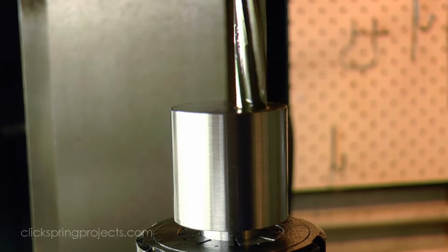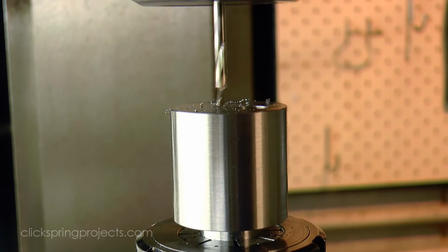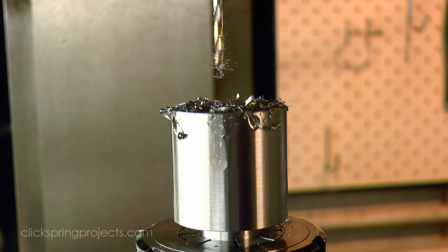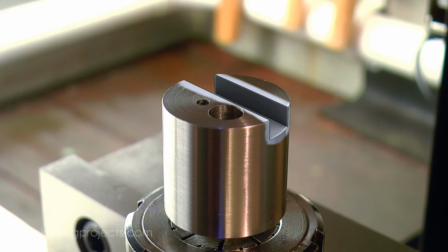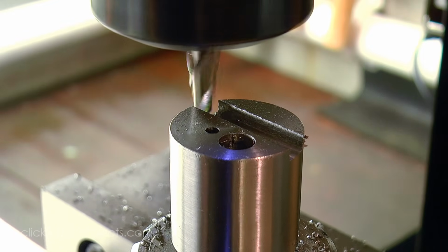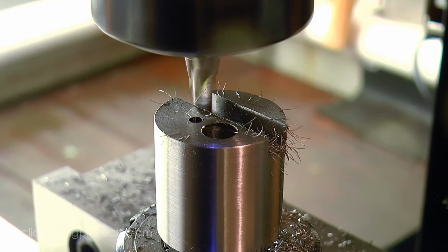Now, despite its primary role being that of carrying multi-tooth blanks, much like the sharpening tool, the arbor has been designed to serve more than one purpose. For example, you'll notice that it has a small channel sunk into its face. This allows us to use the tool to also produce simple fly cutters, using the exact same button tools and calculator that we're using to form the multi-tooth cutters.